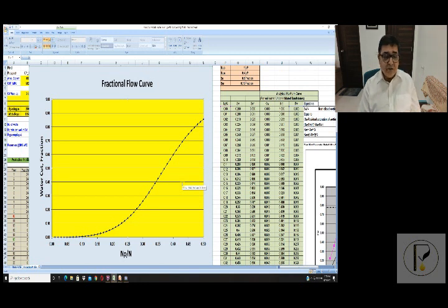Another way can be, reservoir temperature is extremely high, or maybe surfactants are not conducive to such reservoirs. So after the end of a good water flood like here, if it's a light oil like this, 1 centipoise or less, well, immiscible carbon dioxide.